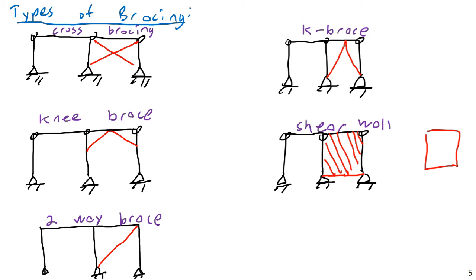And so the easiest way to do that is to make it out of concrete. Now, there are other materials you can use, but concrete is obviously very fire resistant. And if you're building a big steel building, and you're already having to construct this great big concrete core for fire resistance, you might as well make it carry some shear as well. You'd be foolish to have this great big concrete core in the middle of your building for fire purposes, but then not count it to carry any load and just use, say, fixed connections for everything to carry all your shear load. That wouldn't be very efficient. You could do that if you had all the money in the world, but nobody's really going to do that.